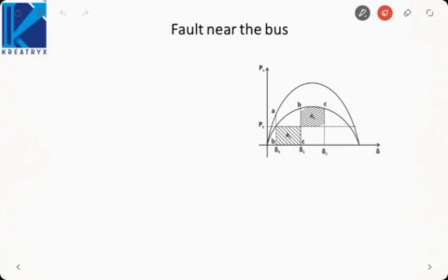Here, first let me show you the power angle curve. This here is Pmax 1 actually. This is Pmax 3. Initially we were operating at an angle delta naught. This delta naught is incorrect. This is the angle delta naught where PS intersects my first curve. Then as soon as the fault is encountered, we go from A to B.